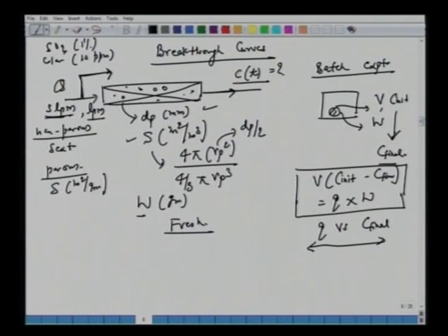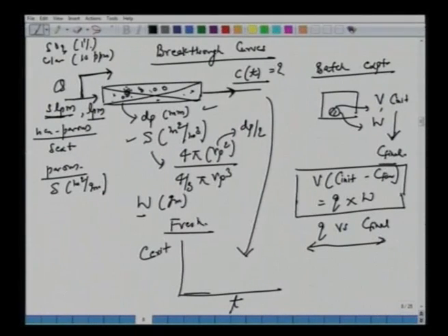All right. Qualitatively you should be able to make out this response. We want to plot T and C exit. For a long time we will not see any concentration here, because, one, the fluid will take some time to reach here, that's the residence time, but even then, when the fluid goes through this fresh adsorbent, some solute will be getting adsorbed here.